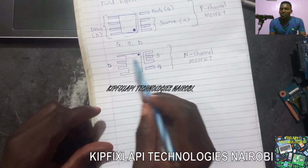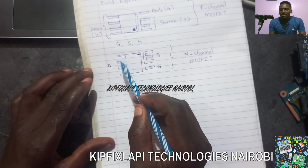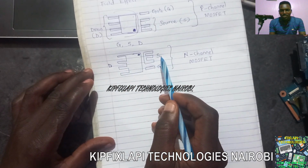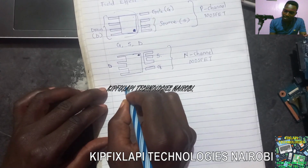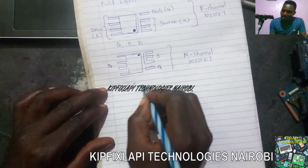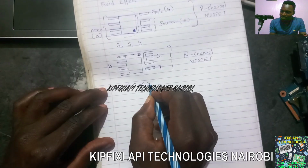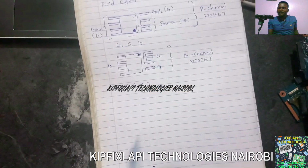So in case you have a scenario where you test continuity, or where you can feel like the drain is connected to the source, it means that component is faulty, right? So you need to know that the drain is not connected to the source, and still not connected to the gate, right?